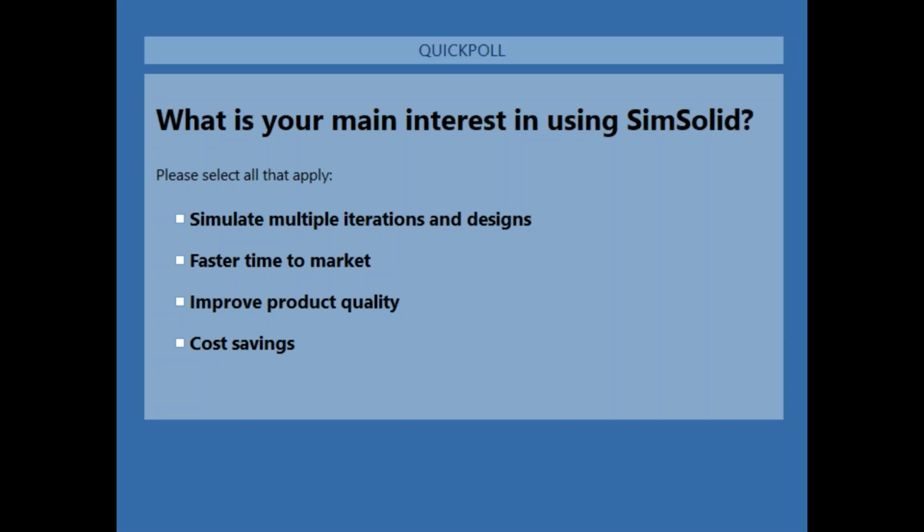Another question: is there any way to improve accuracy other than increasing solution passes? Yes, there are some other methods. We can turn on some additional functions, but I'll cover that if we have another class. So yes, we have other ways to improve accuracy, not just the solution passes. Another question is about anisotropic material. No, we are only working with isotropic material at the moment.